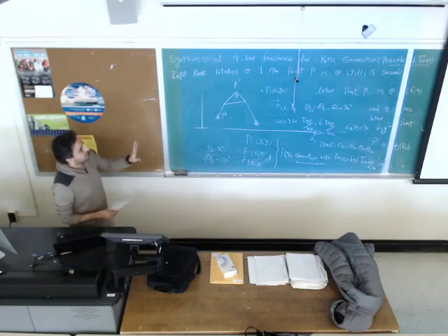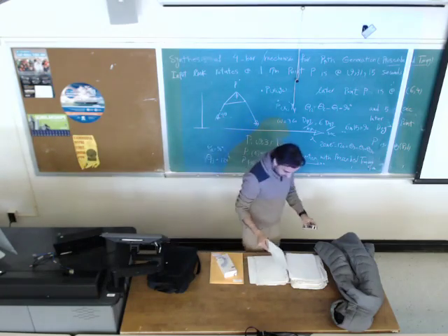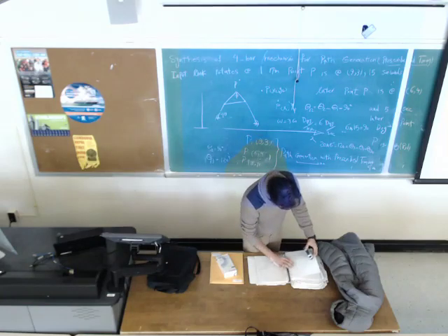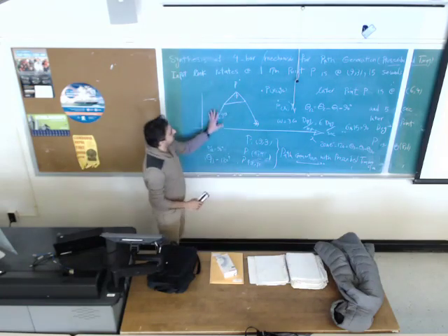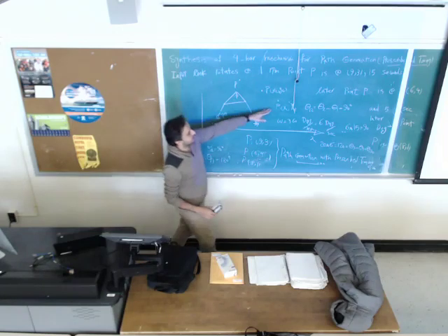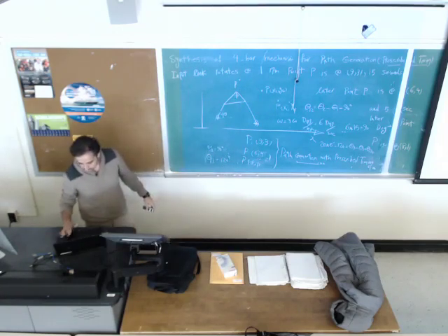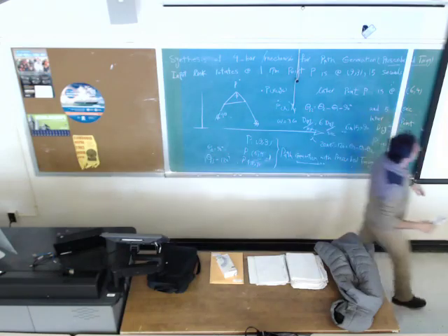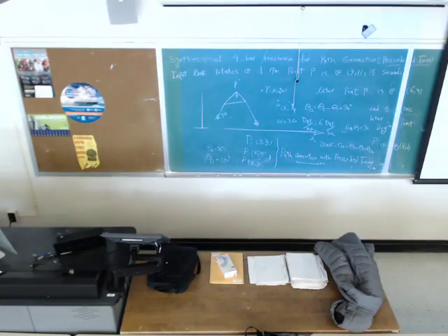All right, it's similar to motion generation. So we would like to design this four-bar mechanism such that it's moving through these 3 precision points. What we are going to do, we define vector V1, vector V2, and vector V3 to reach point P. And from the other side, I'm going to go V4, V5, V6. I divide it into 2 dyads, left-hand side dyad and right-hand side dyad.